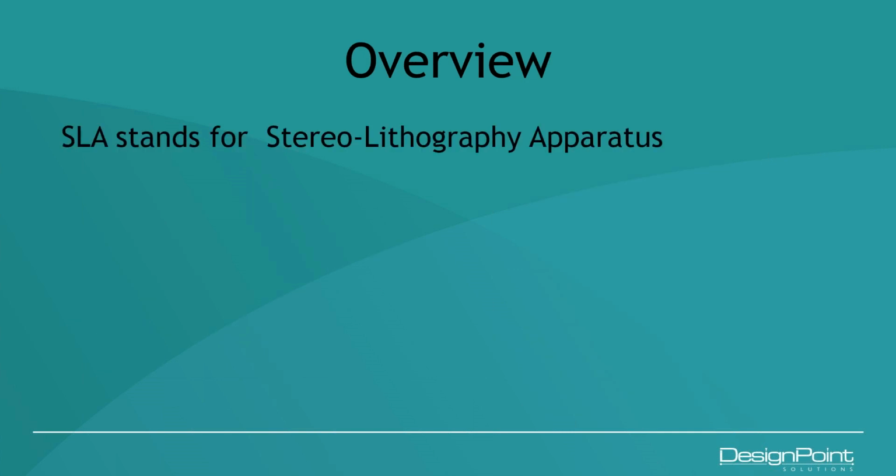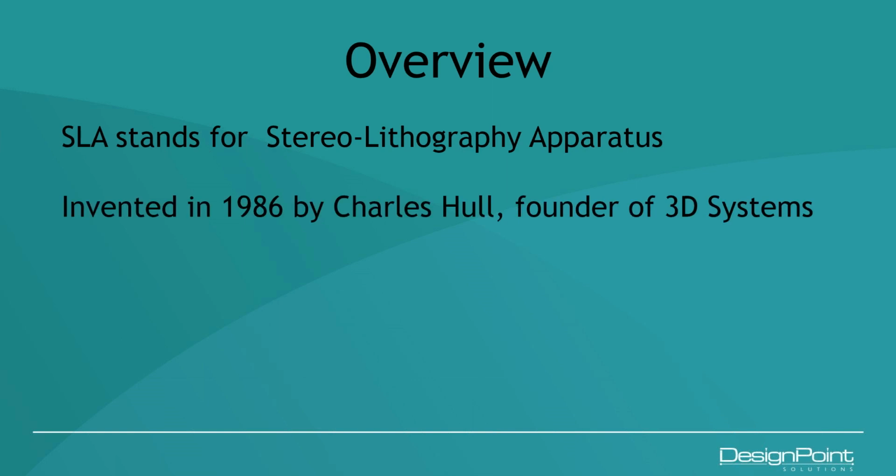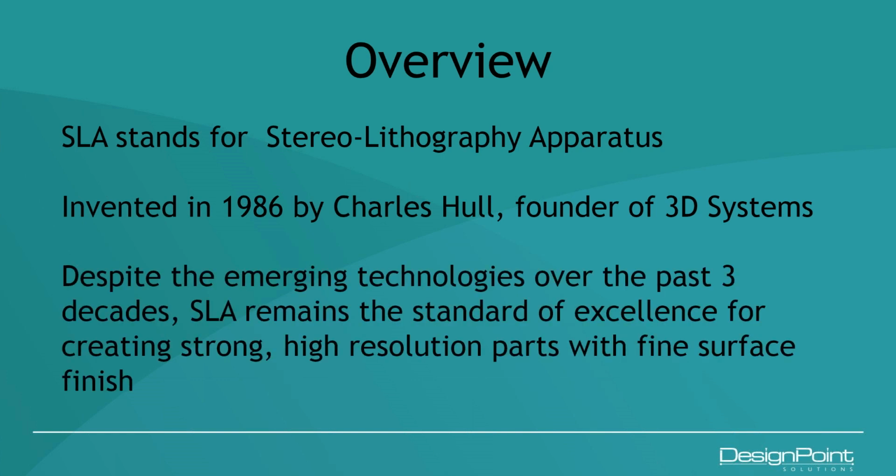So SLA, for those who don't know, stands for Stereolithography Apparatus. It was invented in 1986 by Charles Hull, who happens to be the founder of 3D Systems. So SLA has been around for around 30 years now. And despite the emerging technologies over the past 3 decades, SLA remains the standard of excellence for creating strong, high-resolution parts with fine surface finish.